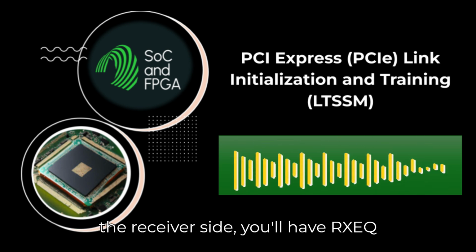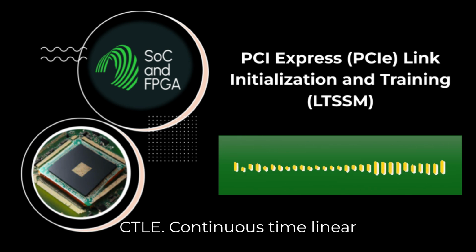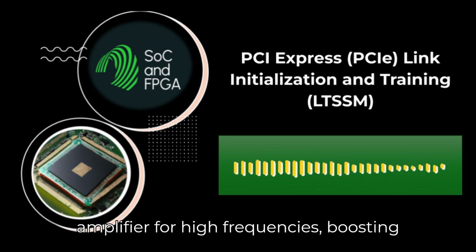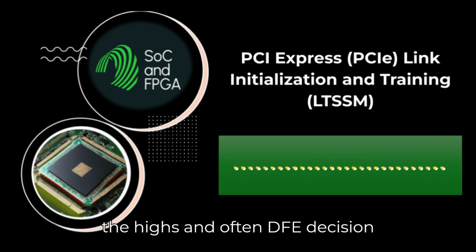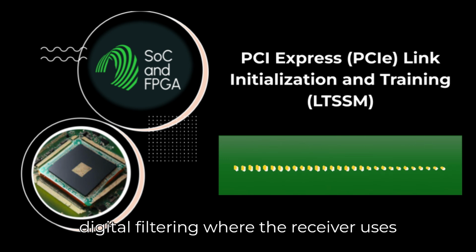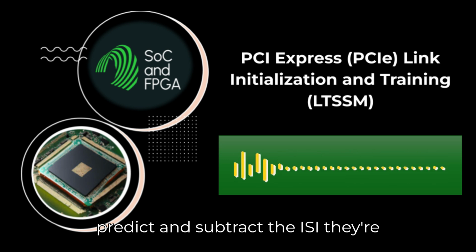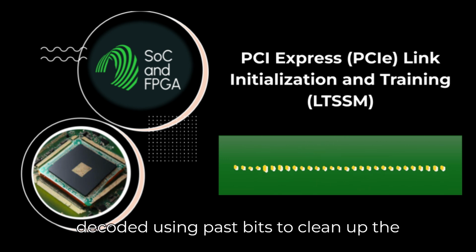On the receiver side, you have RxEQ, receive equalization. This might involve CTLE, continuous time linear equalization, which is like an analog amplifier for high frequencies, boosting what the channel attenuated. Okay, boosting the highs. And often, DFE, decision feedback equalization. This is clever digital filtering, where the receiver uses the bits it just decoded successfully to predict and subtract the ISI they're likely causing on the current bit being decoded. Using past bits to clean up the present bit.